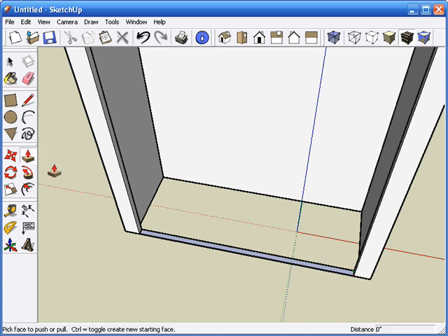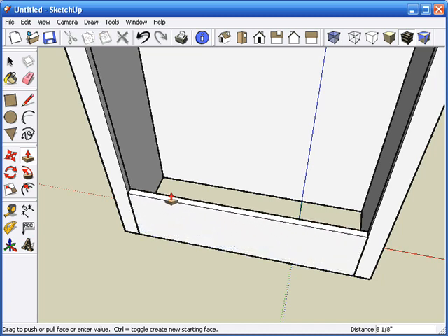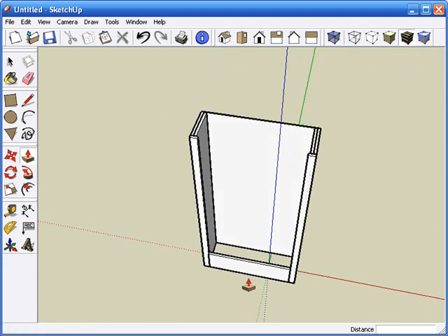So now I'll take the push-pull tool, put it over that rectangle until it turns to dots, and bring it up. Let's make it 8 inches tall. So 8 inches. And notice it says 8 inches exactly. We can trust that. We don't have to type anything in. If it doesn't have one of those little squiggle marks in front of it that means approximately, it's safe. We can use that dimension. So now we have the top style. Now we have the bottom style.